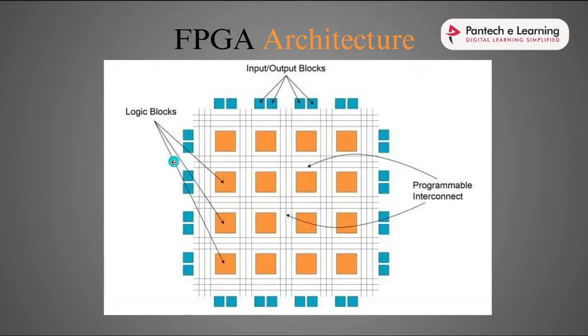So I am using these three pins to give the input for a full adder, and then I will use these two pins to get the output for the full adder, sum and carry. Inside the CLB, it has some lookup tables, muxes, and flip-flops. By using the Verilog code I am assigning this, so in this CLB we have to follow this.